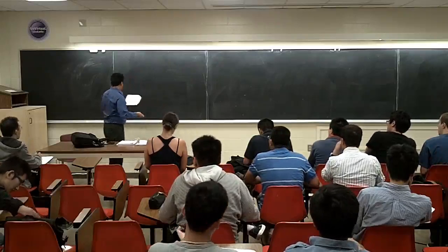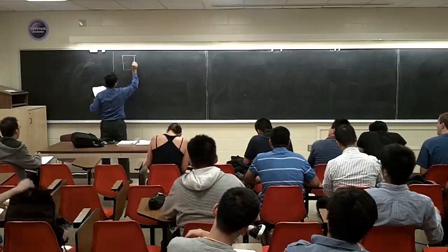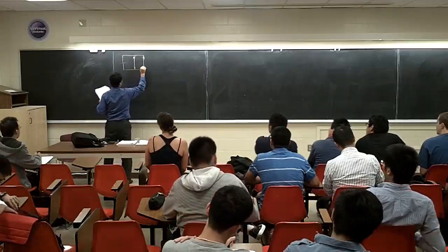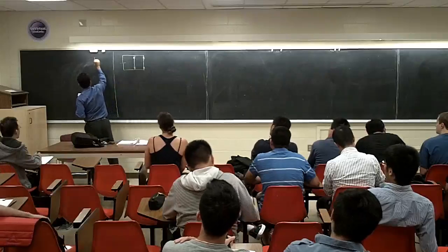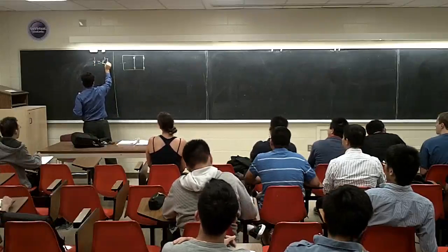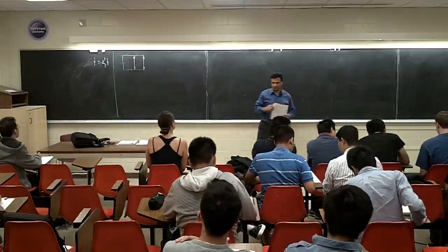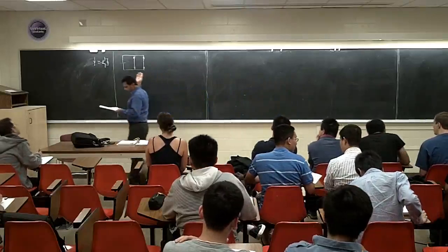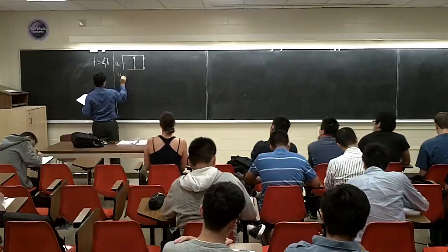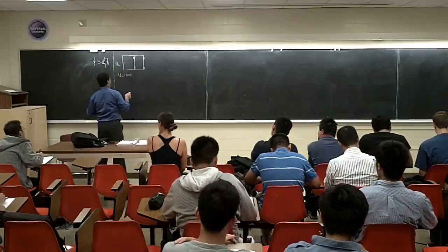We said we have an inverter, full bridge inverter. Sometimes to make my life easier, I use this one. If I put this cross here, from now on, you see that one across means the switch with anti-parallel diode. So it says we have a full bridge inverter, VDC, this is a DC bus. VDC is 100 volt, and it's supporting an RL load.